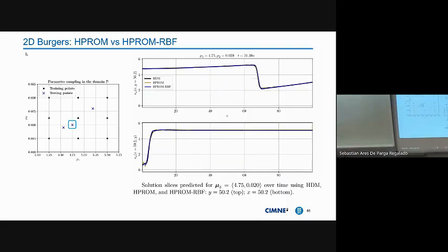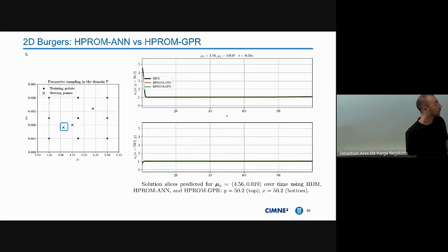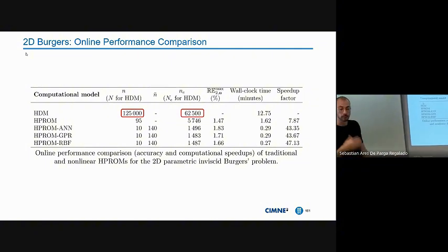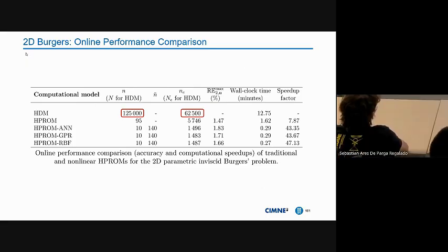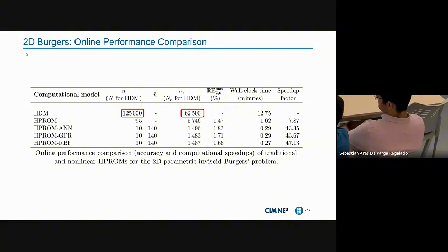I also tested the hypersonic case that I was showing at the end, where we are varying the Mach number. We are testing with 16 different Mach numbers. I also tested the flow past a cylinder with different inlets, and it was working pretty well. Sorry, just one thing that you asked: I never checked the time step, not that I remember. A lot of people report it is a problem depending on the mathematics in the time step. Just do not make it a multiple. Make it 1.7, 1.3, something like that.